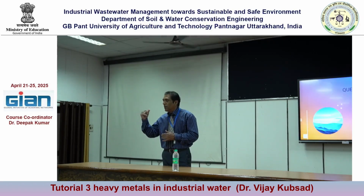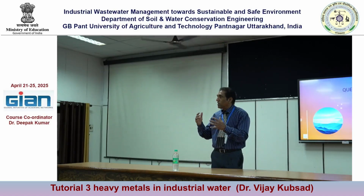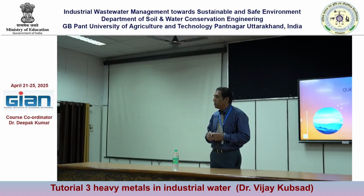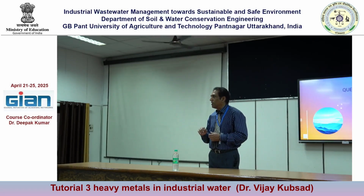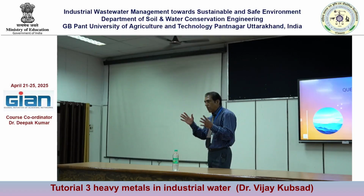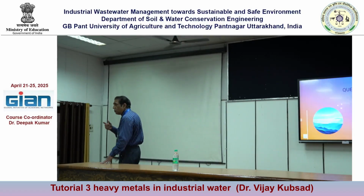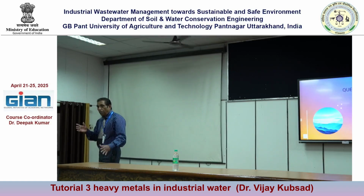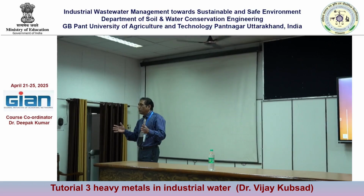If they are producing low BOD and high pH or low pH water, and non-cooling tower wastewater is coming in, you can mix. If it is a cooling tower, they have a TDS issue but they don't have BOD. Right? You will remove TDS and then discharge. That is the example I gave. It is the same concept as the common treatment plant, where the city also does the same thing.